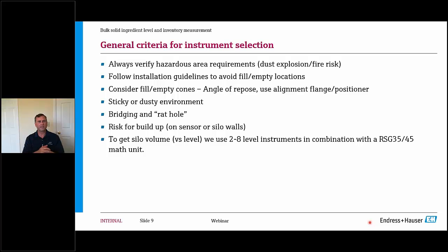So that's kind of a step one, safety first, so to speak. And then you need to look at the installation guidelines. There are some basic things. Clearly you don't want to put the sensor right in the path of the filling nozzle, so that the product is falling directly onto the sensor, which could then give wrong readings.